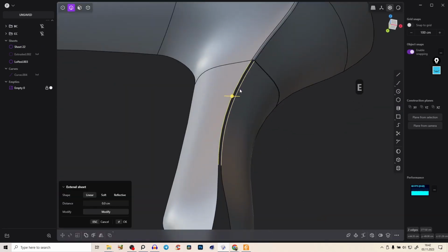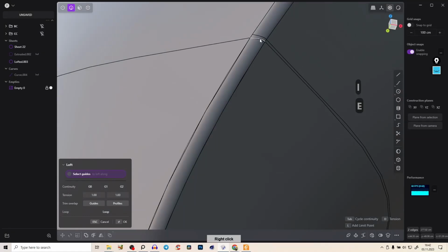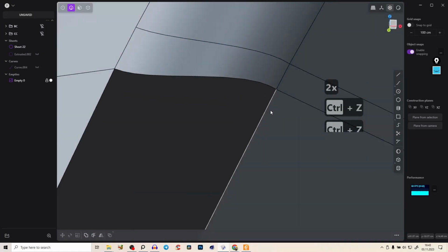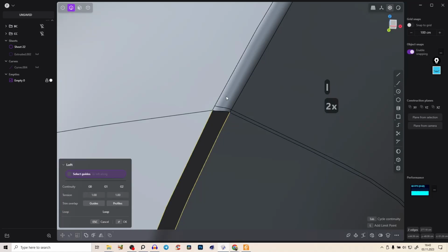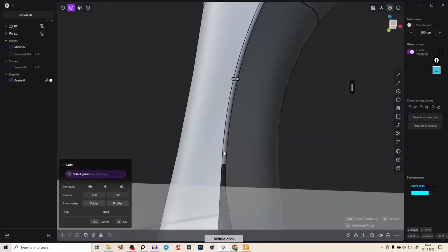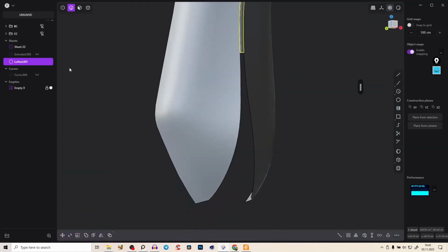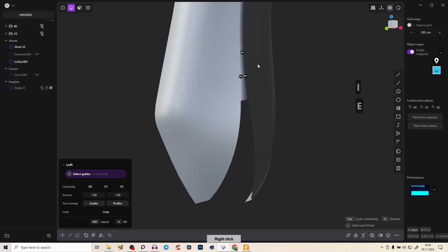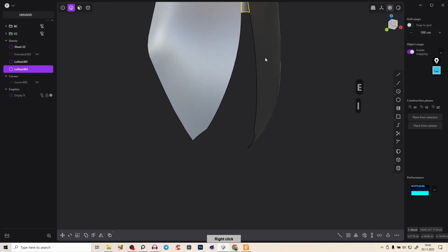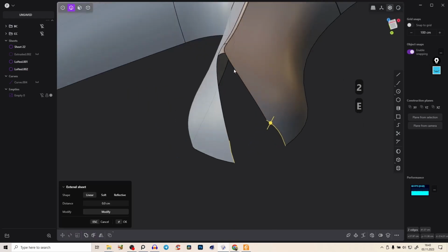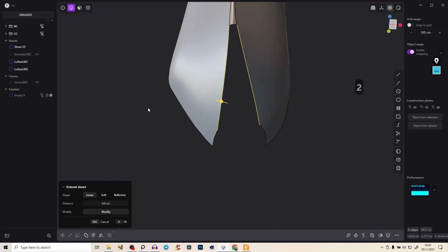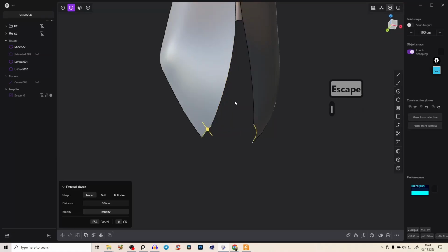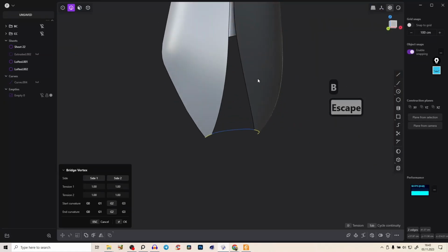And let's also loft those edges here, and again we have a little extra edge. So just try to delete this, and let's loft, Shift click. And we are coming to this end. And here we have one more edge, Shift. Before we loft that, let's first loft this endpoint, because otherwise it might go a little bit crazy. So let's create a guiding line from here to here, Shift B with G0 continuity.